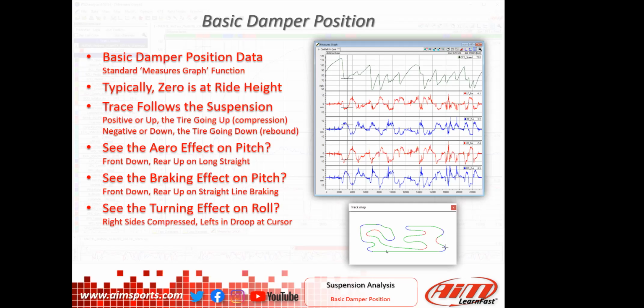Gosh, you can see some spikes here all of a sudden in spots, and those are where he is maybe using a little bit of extra curbing, either at the apex, if it's on an inside tire, or hitting something on the outside, and all of a sudden the suspension will come up on an exit curb. We can see how fast those things are happening. We can see how much he is using. There's some pretty big hits over here in this right front that goes right up to the top of the travel window. Again, just all stuff that I wanted to kind of show you.